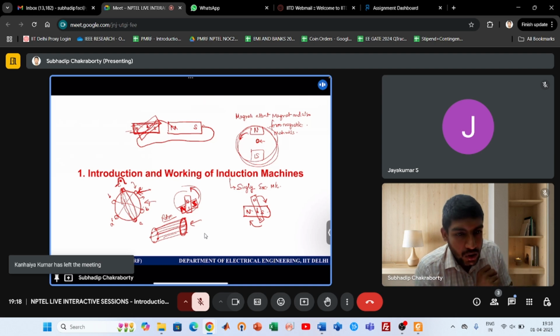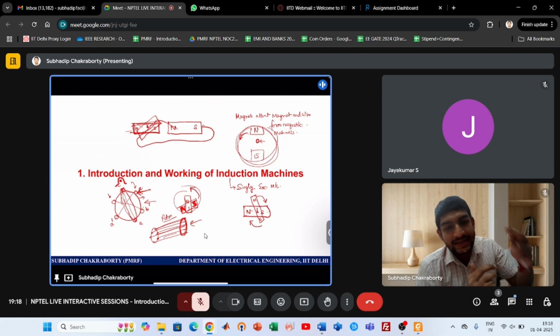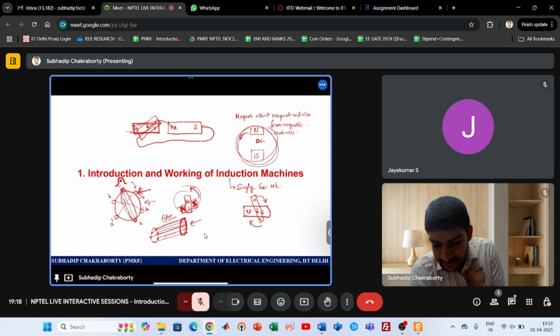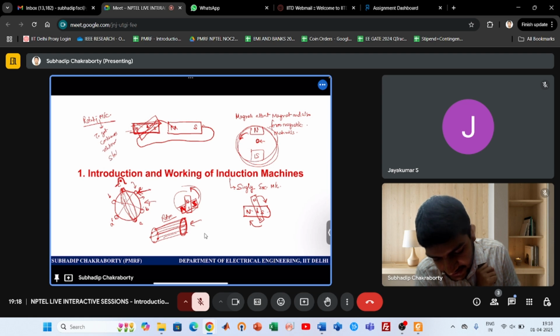So that is the way Lenz law works: the rotating magnetic field will be opposed by the rotor through the rotation of the rotor. And the rotor will virtually get induced EMFs and produce poles, fictitious poles. And you know that for a rotating machine, the generalized theory of rotation says that to get continuous rotation, stator and rotor MMF need to be stationary in space with respect to each other.